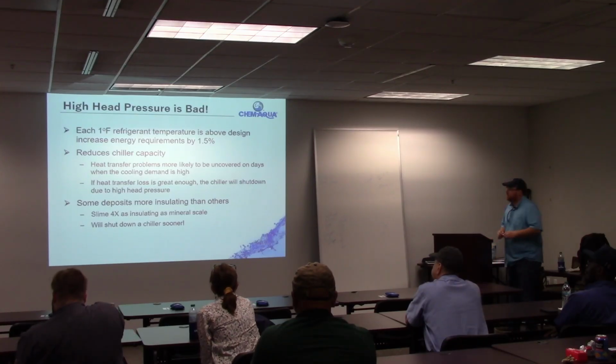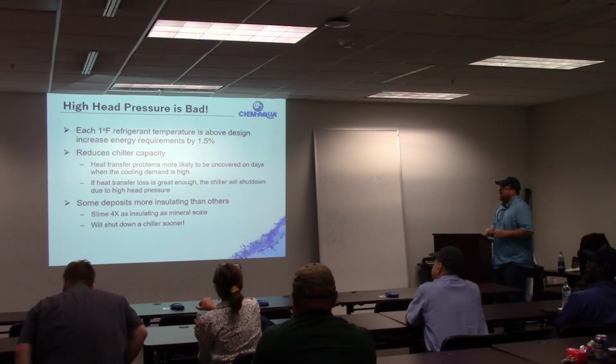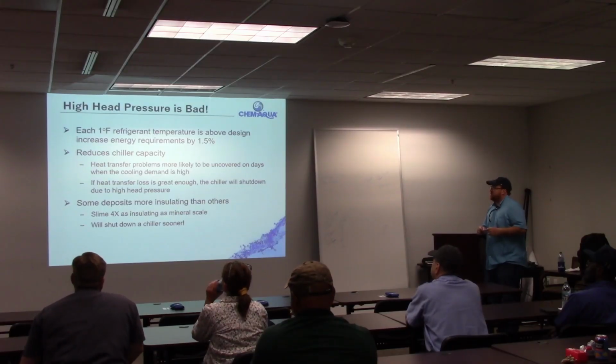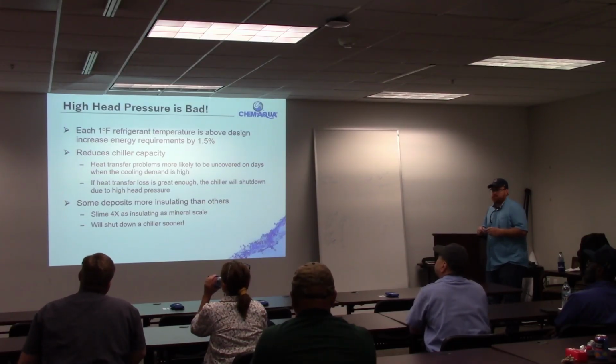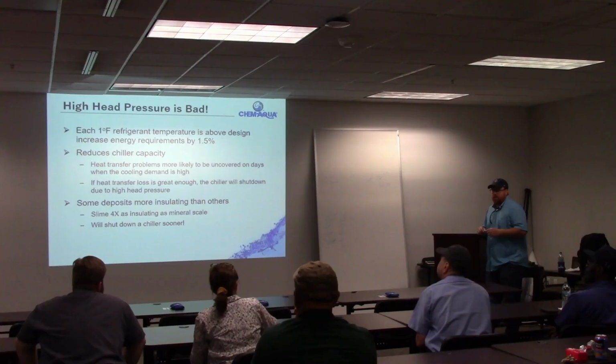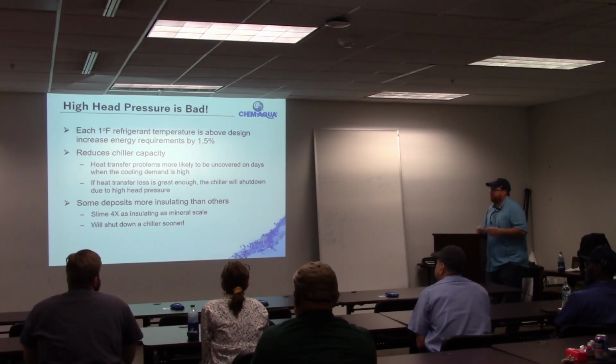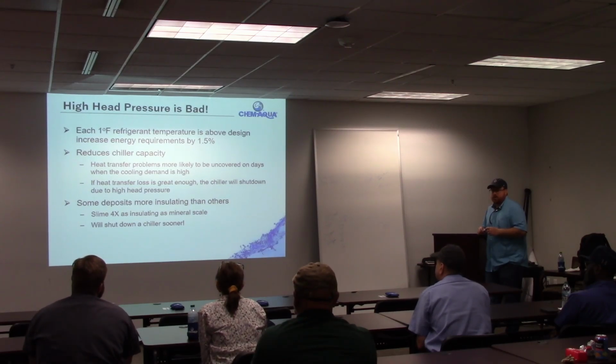This is just good to know. Each 1 degree refrigerant temperature by design increases energy requirements by 1.5%. That illustrates how your costs go up just by 1 degree of increased approach temperatures.